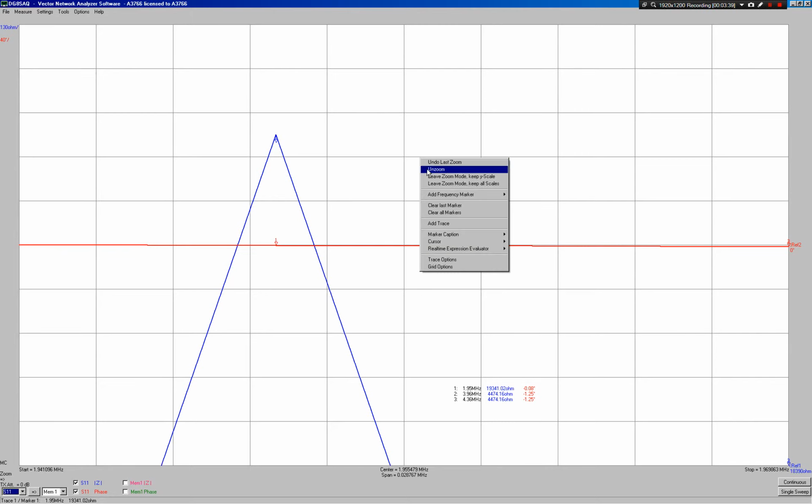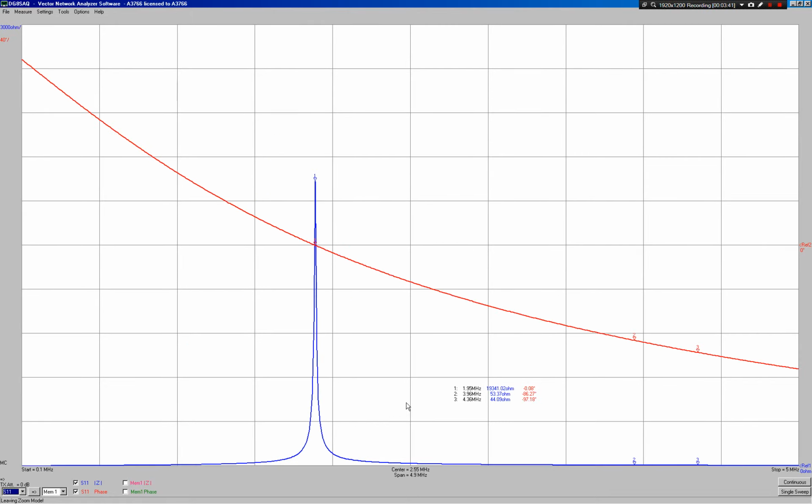Okay, that'll be fine. So we're at 1.95 megahertz. Good. Interestingly, where I'd set it is almost exactly the same as the fundamental resonant frequency of the secondary. So I'm going to put this back on continuous scan now, and I'm going to gradually shift. So that's scanning.